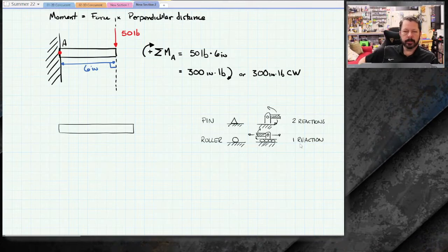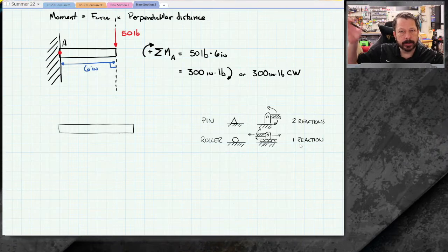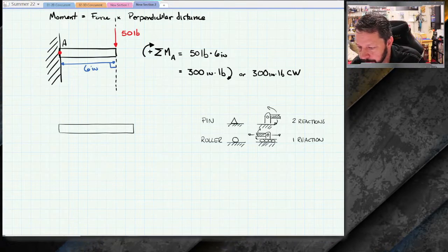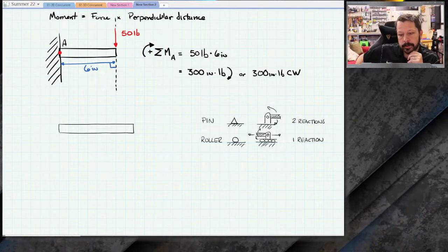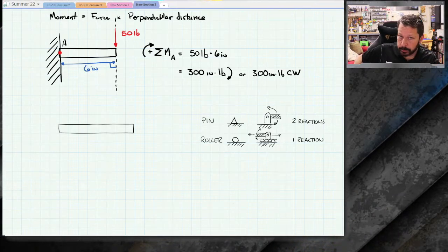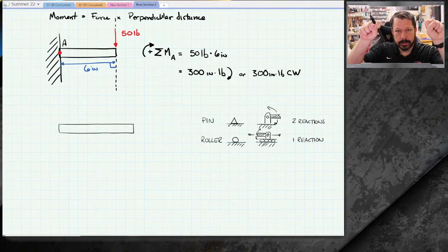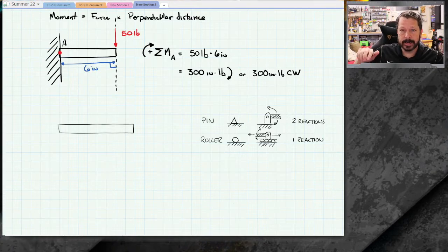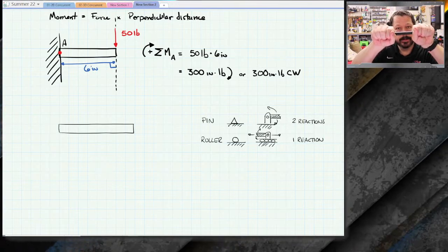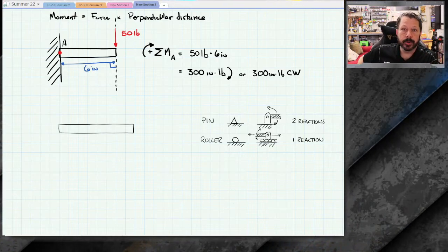And that seems like, well, if you're building a bridge, why don't you just bolt both ends down? That would make more sense so it doesn't slide around. But in the real world, there's a need for metal objects in particular to be able to move around. If I constrain both ends and we're out here, it's 100 degrees outside, and it's a metal thing between those, that thing's going to want to expand, and it's going to generate some extra stresses in there. And that's going to be a big problem, right?